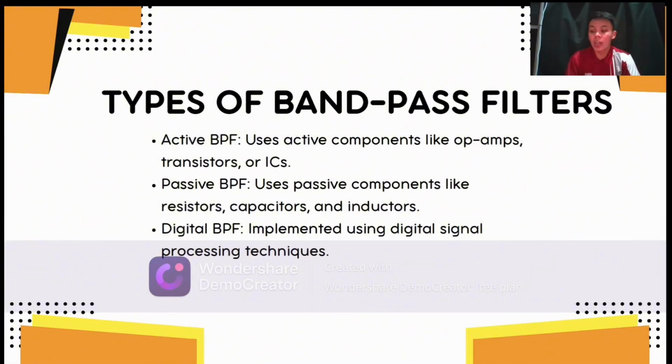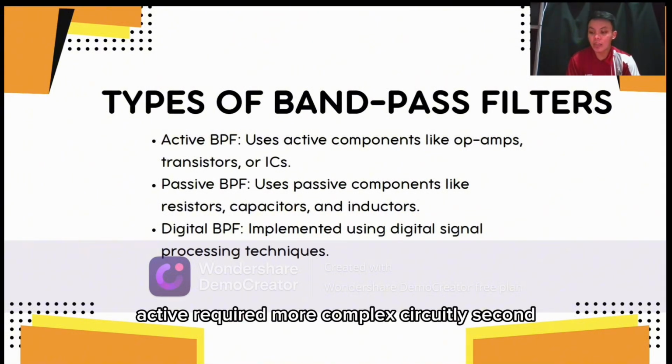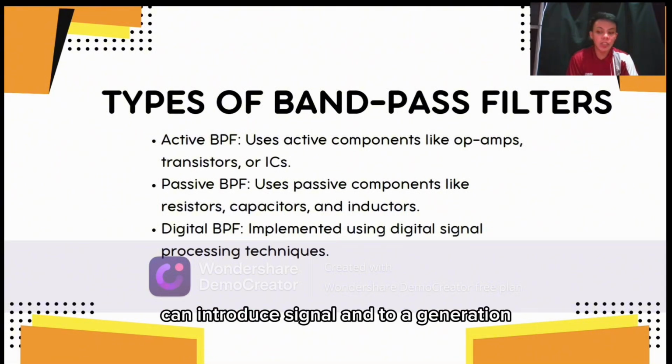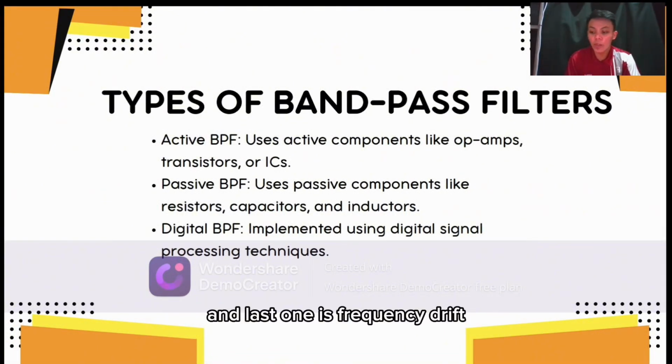And there are also disadvantages of bandpass filters. First, component complexity: active filters require more complex circuitry. Second, insertion loss: they can introduce signal attenuation. And the last one is frequency drift: they can be sensitive to temperature and component variation.